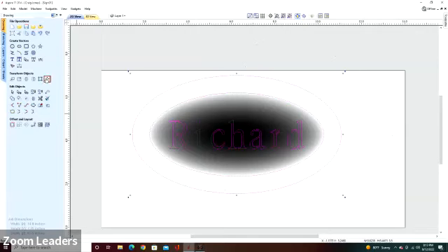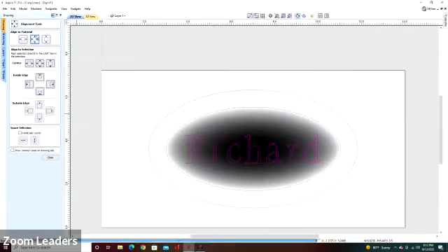There's a tool in here that says, okay, I want to center all this on the middle of my workpiece. Now, Richard also mentioned earlier that you need to tell the system where the origin of your work is going to be. Two places are very common. One is in the center of the piece. The other is at a position typically at the lower left-hand corner where X and Y cross at 0. And for this particular one, this is going to be our origin.